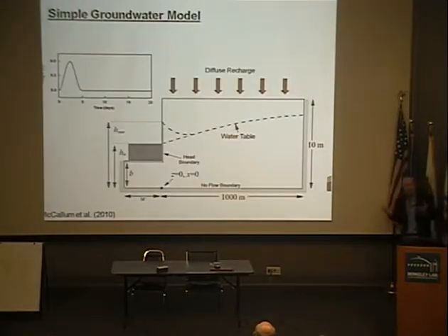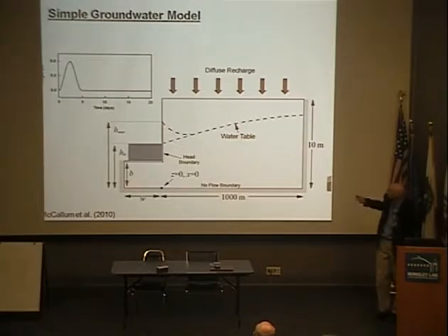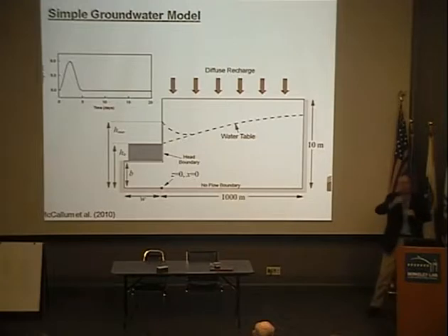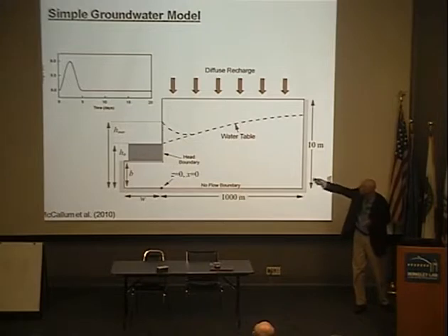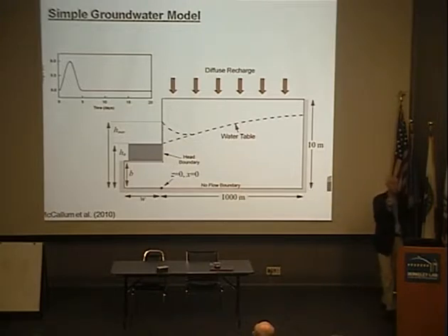We've done a little bit of modelling on that I just want to mention briefly. So this is just our cross-section through a stream. This is the aquifer, the stream sitting here. And we've just looked at what happens as the water level in the stream goes up and down through a storm event, just with a sine wave variation in head in our boundary here. So we've assigned different concentrations to reflect the river water and the groundwater.